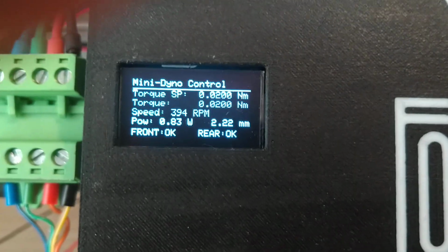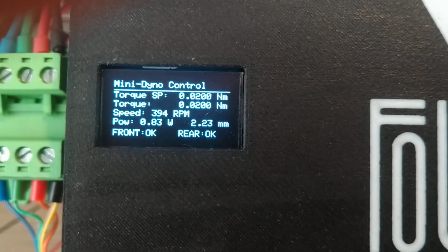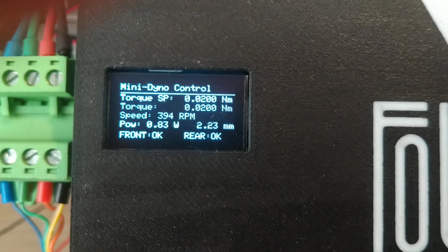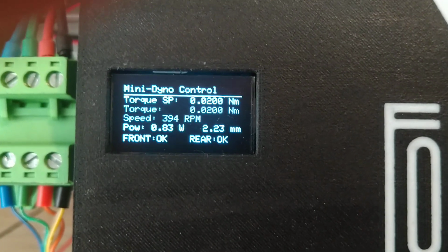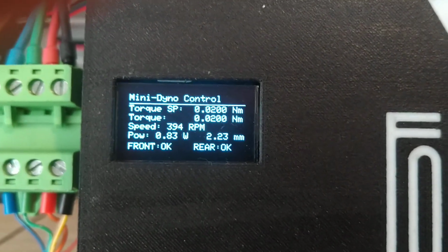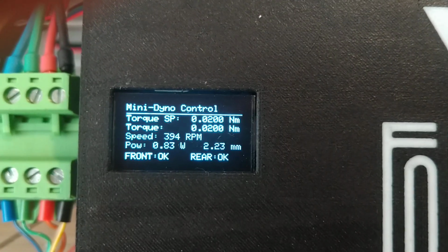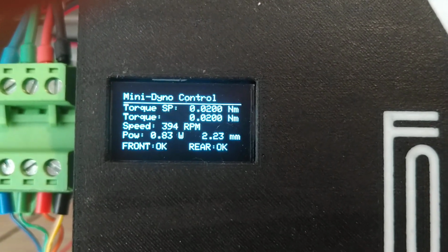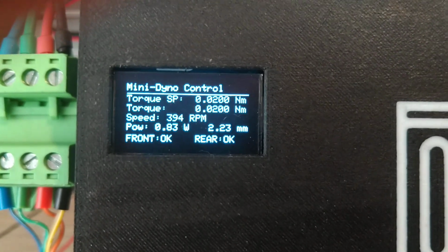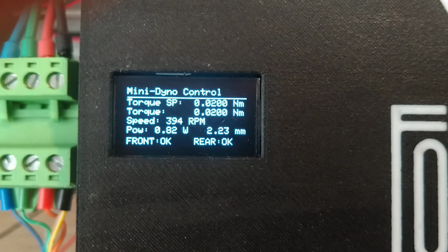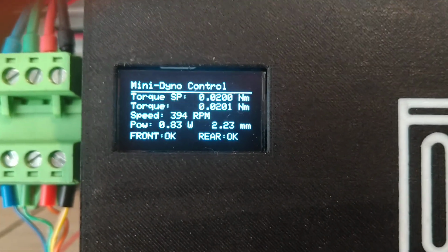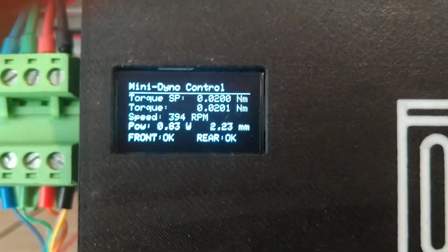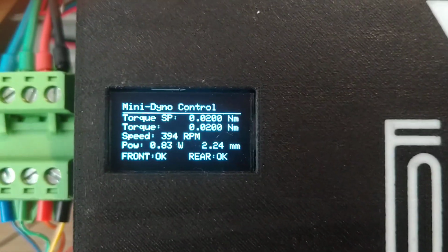And as long as speed remains unchanged, the system would be sitting at pretty much this gap. However, since over time the copper will be accumulating heat, heating up a little bit, it would require a little bit shorter distance to generate exactly the same resistance level, so the system would automatically adjust the gap to compensate for temperature increase.